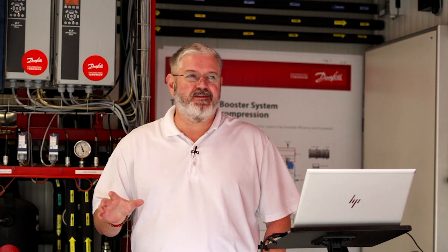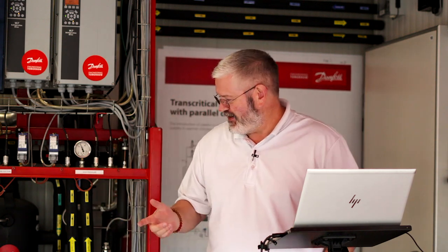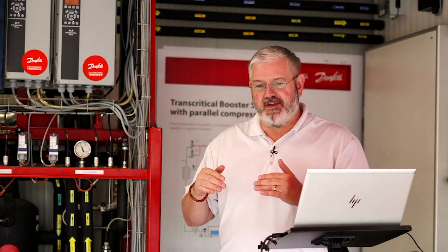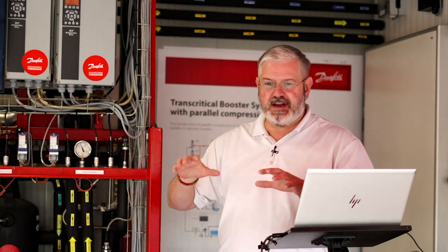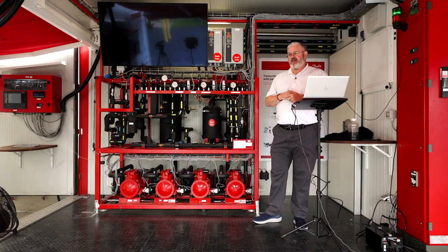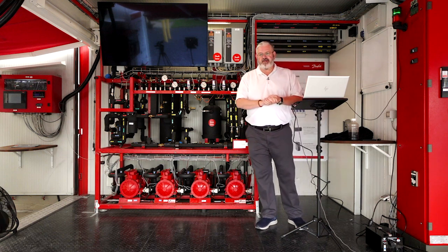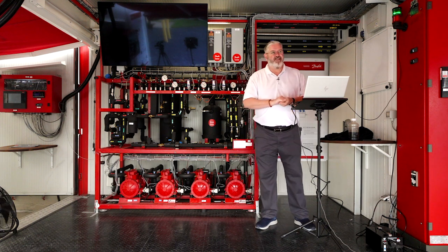However, I can speak to the startup side, and I see people struggle with the oil. Everybody knows if there's an oil problem, you need to dump in 2 more gallons, or that's the common misconception. It's pretty common. People put in more oil than they should because the pressure switch wasn't defined correctly. There's some other issue, and they wind up having to take that oil back out of the system. So I see some issues with people getting the oil portion right. And then service-wise, I don't run service in that way. I kind of support startups and things like this. So I don't have a good answer, and I'd rather be honest.